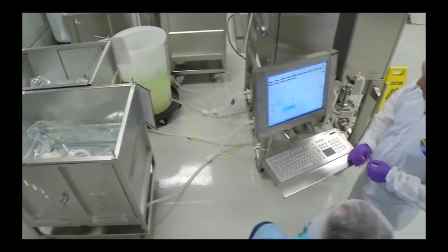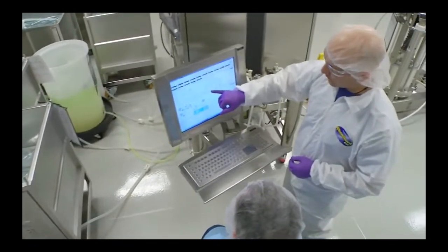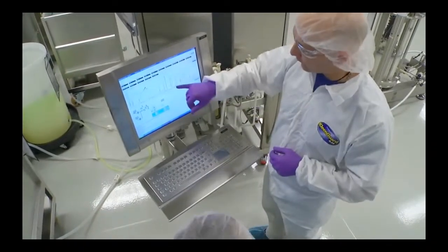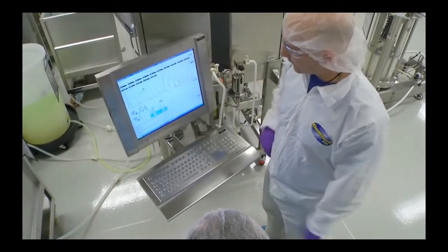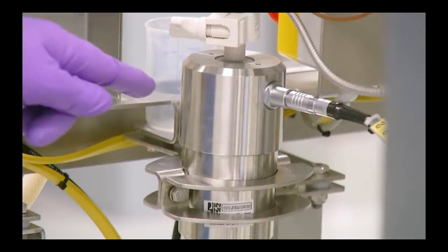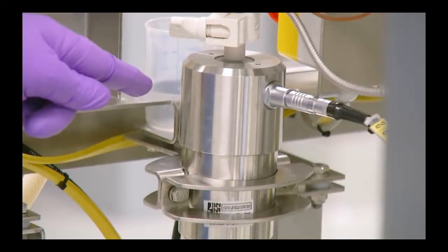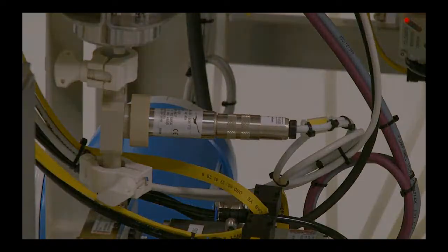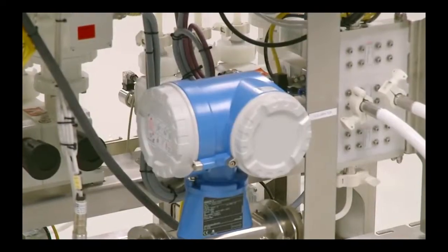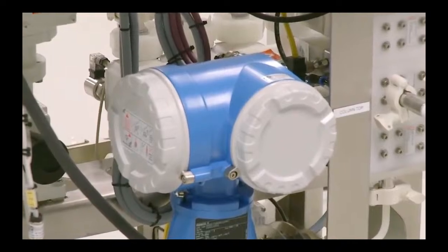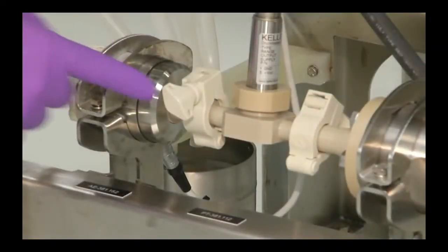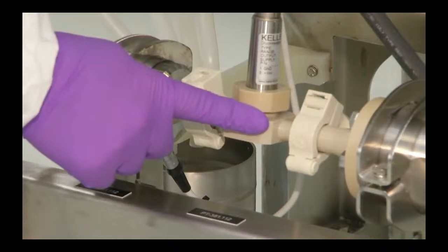To help monitor the chromatography equipment and the solutions flowing through the unit during the process, a number of sensors are located along the product flow path. There is an electrical conductivity sensor at the column inlet, a pressure sensor just before the pre-filter to help identify a filter clog, a flow meter to measure the rate of solution movement through the column, and an air sensor to ensure that no air has entered the flow path.